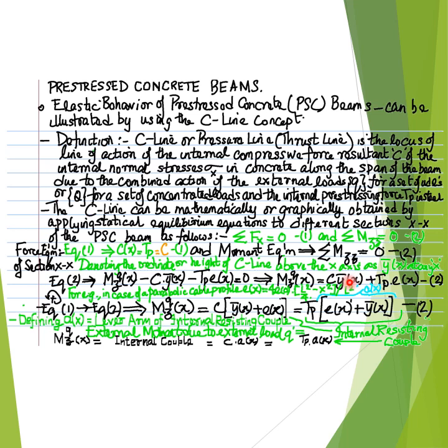As a special case, a straight pre-stressing cable profile or a straight pre-stressing tendon profile will be described by a constant value of the eccentricity function, that is, in case of a straight cable or straight pre-stressing tendon, the eccentricity function e with the argument x will be simply equal to a constant, depicted as e in the figure or the solved example presented in one of the earlier slides.